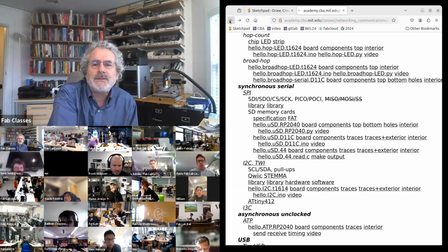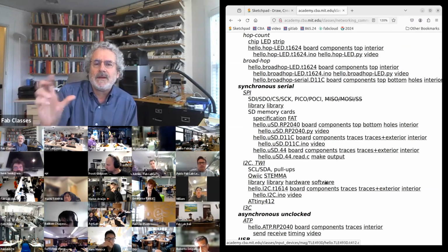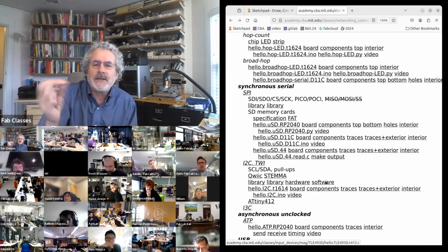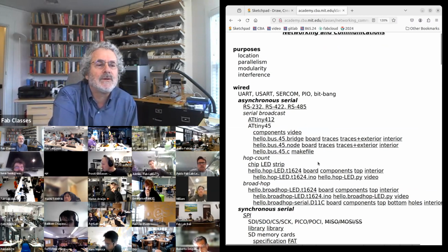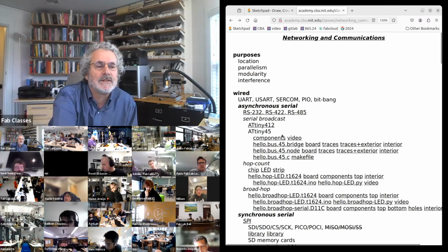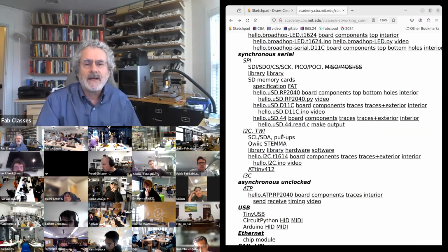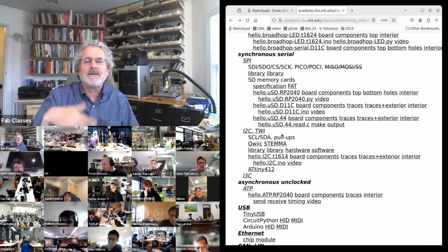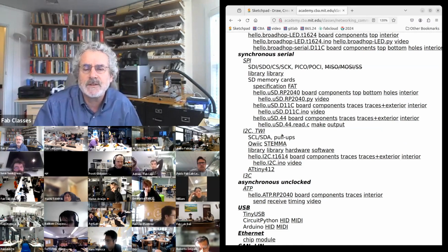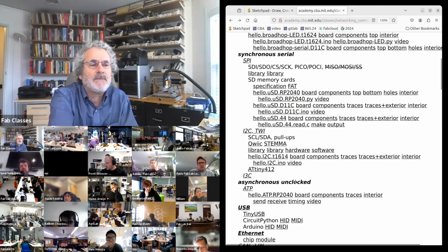So I2C lets you connect devices where each device needs a hard-coded address. So a bit like what I showed you in this first serial version. You need to have a fixed address, and many of the parts you buy for sensors or actuators speak I2C, and they have standard addresses built into them.